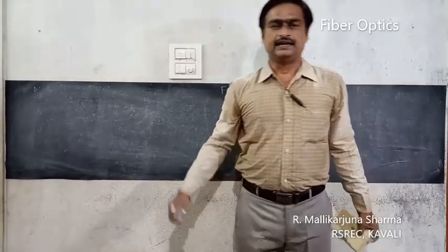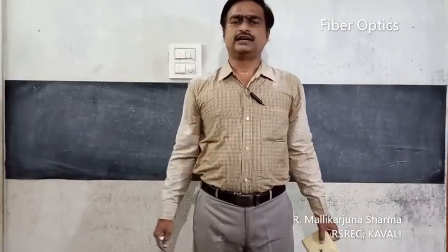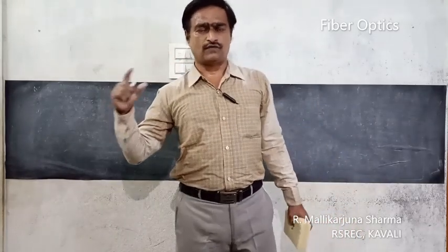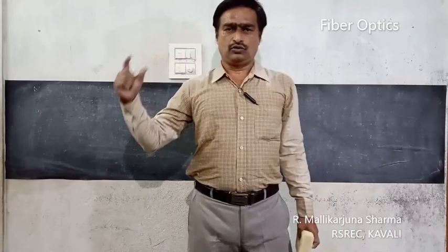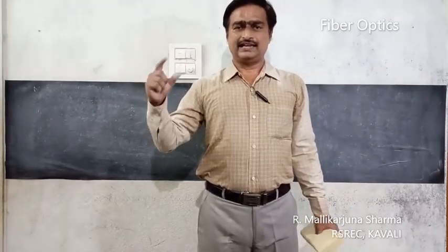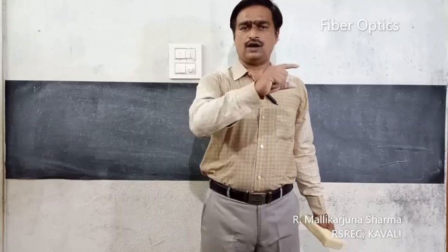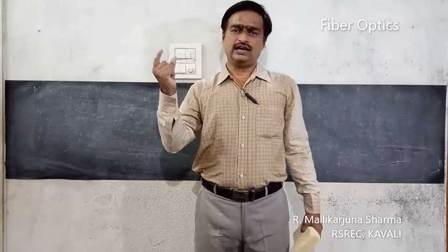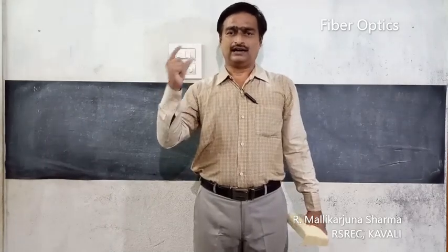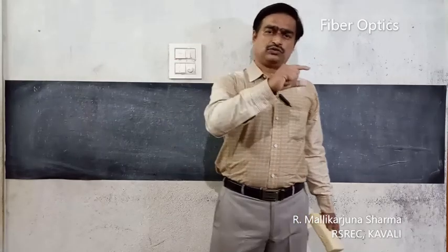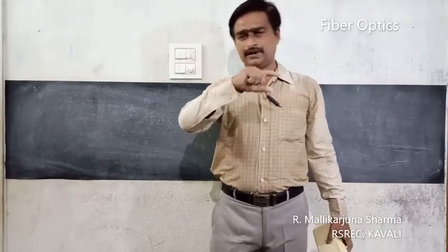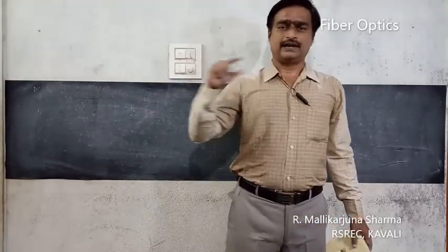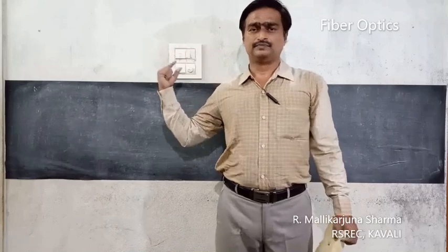Applications in the medical field, they are mainly used in endoscopy. Okay, that is endoscopy. It consists of two coaxial layers of optical fibers. One to carry the light rays from a source to the object of observation, then the second cable from the object to the screen or our naked eye. That is, to take light rays we are going to use one optical fiber, to receive the light rays we are going to use another optical fiber. Okay, that is the composition of this endoscope.